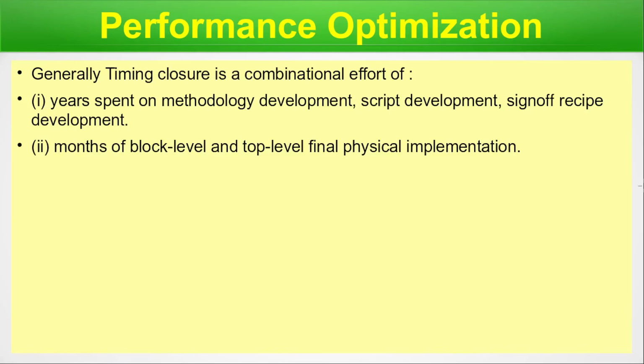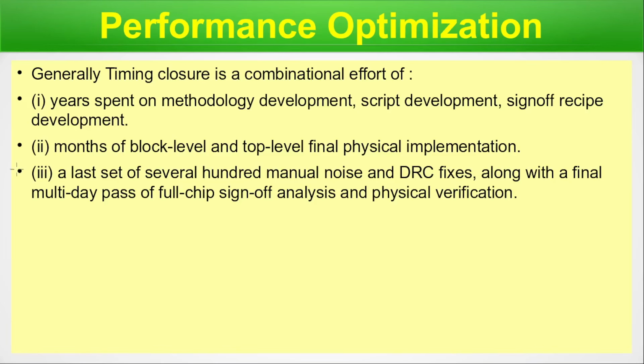Here we spend months to make the physical design part error free from every aspect, and the timing, that is the post layout STA, has to be very efficient. Next, we have a set of several hundred manual noise and DRC fixes. These are fixes that we keep looping back and forth between 2 or 3 steps. That means maybe layout, then DRC, then LVS, then again layout, then DRC, LVS. Maybe some amount of engineering change order also comes.